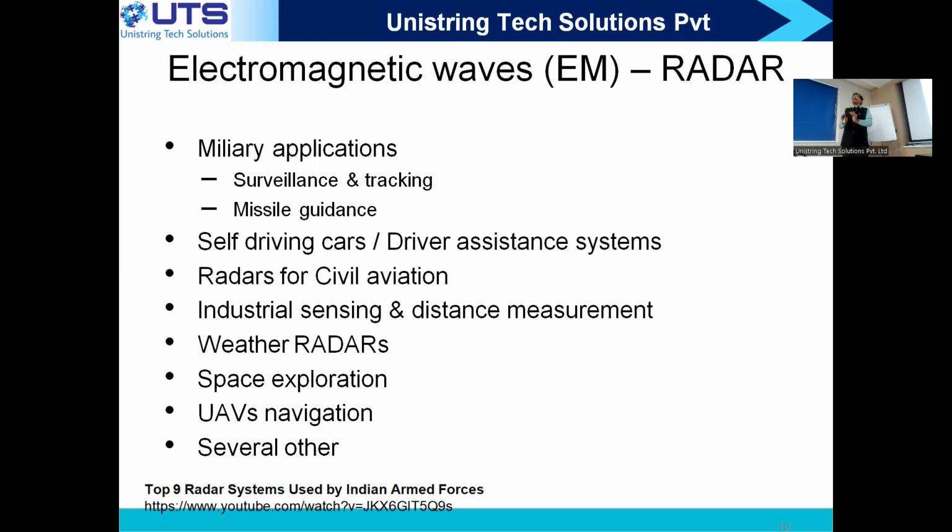A certain frequency band is good for that, so weather radars are designed for it. And that's the interesting thing. When you study the different types of radars in electromagnetics, the choice of frequency will be specific to the application. When you want long-range detection, like 1,000 kilometers for an aircraft, you may choose L band or S band. When you want very precise tracking for gun control and all, you will go to Ku band or Ka band, on the order of 20 or 25 gigahertz. Because as the wavelength reduces, your preciseness in measurement improves.